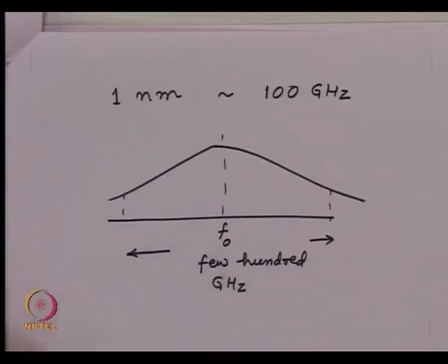So now essentially we take this fact into consideration, that the optical carrier has a spectral width which is very large compared to the modulating signal frequency, and as a result the sideband will not be clearly visible. We will come back to this point little later, but at this point it is very clear that when the signal is transmitted on the optical fiber, a simple understanding which we have for radio frequencies will not be applicable in this case.